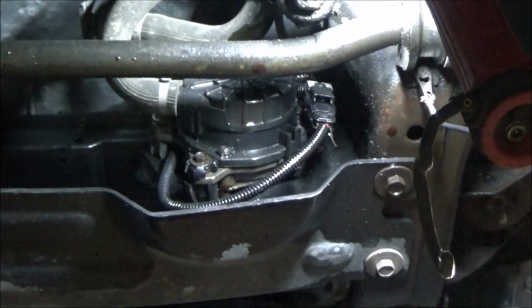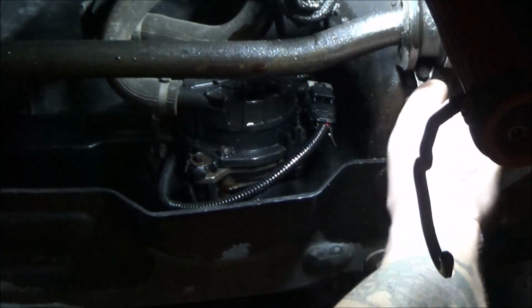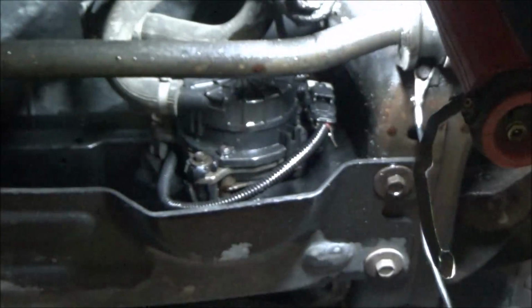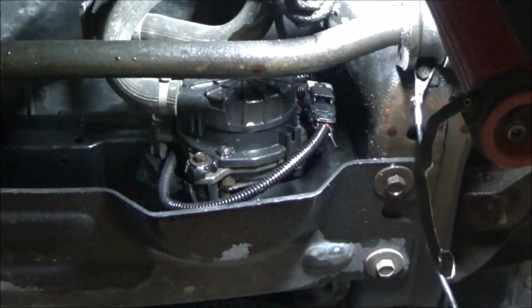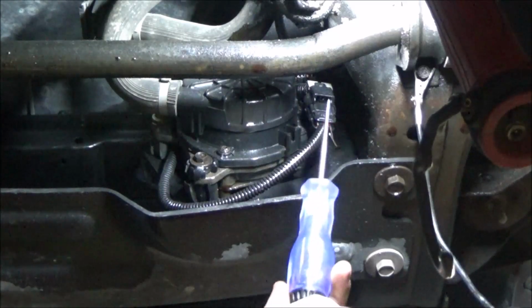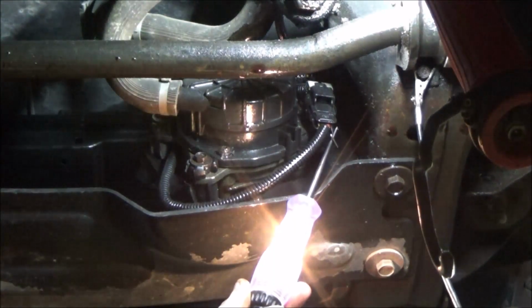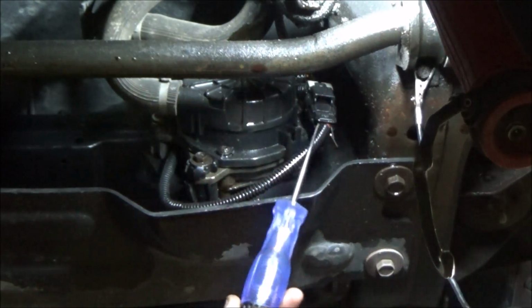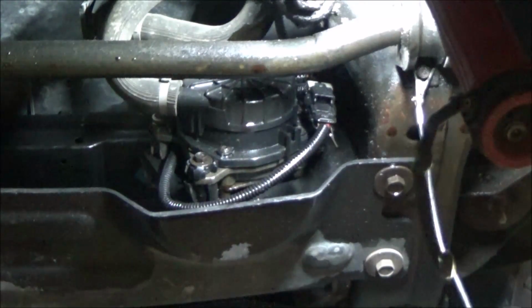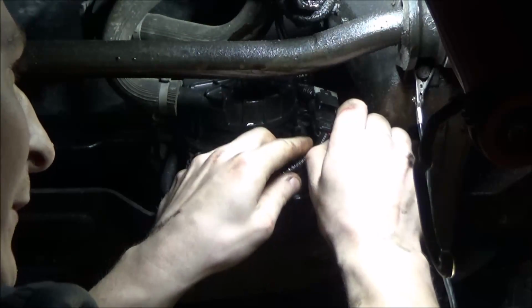And depending on the results of this, guys, we need to check our test light for sure. If our test light does not light, we're going to need to find a good power feed and double check that. So our air pump relay is currently on right now, guys. So if we do have power on this red wire, this test light's going to light. Test light to ground, I'm just going to touch this. And as we can see, this test light does in fact illuminate. So one last check to do on this motor here, guys, and that's going to be this black wire.